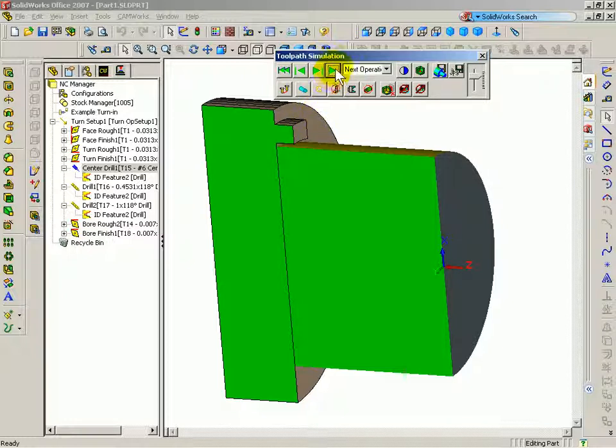Okay, so we would click the next operation where it comes in and center drills. There's a pre-drill, and then we have a larger drill. Then we come in and start roughing. And let me change this tool here to shaded mode. And there we're coming in with a boring bar or a cutter, and we're cutting out or roughing out that segment.